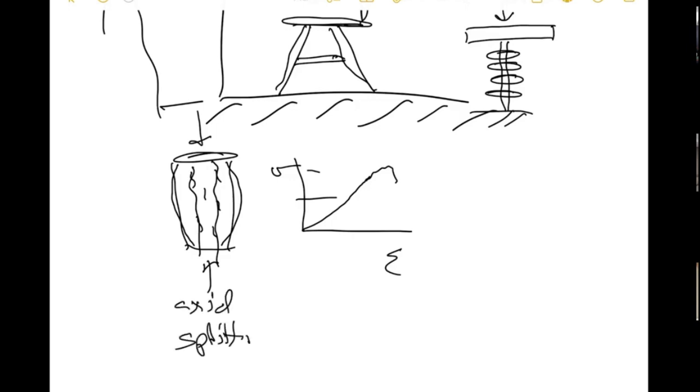But if you took that same rock specimen and put bands of steel around it, now it's inhibiting the bulging. And so the result is it's not able to fail the way it wants to fail. It's going to be stronger. It turns out that rock, not steel, but rock, locally, internally at the grain scale, is pretty much almost all microtensile failure.